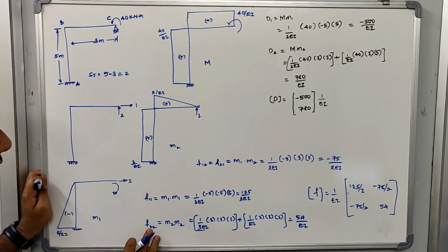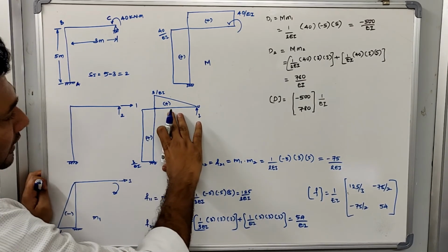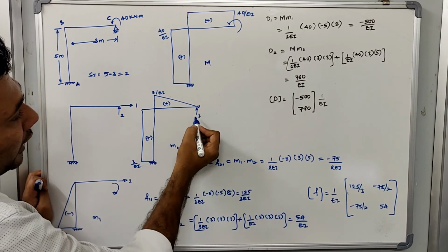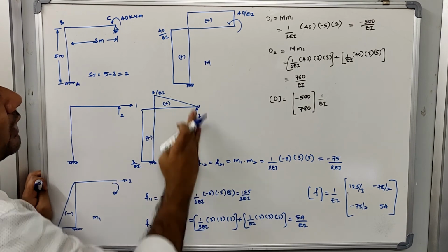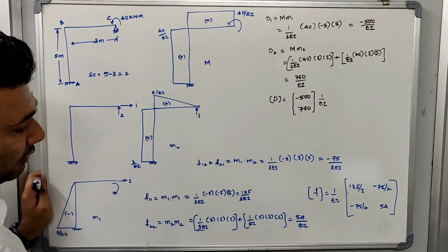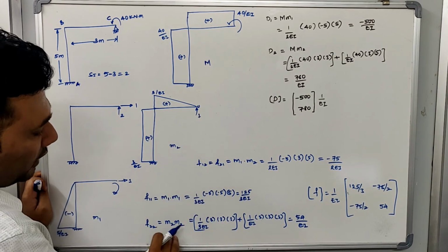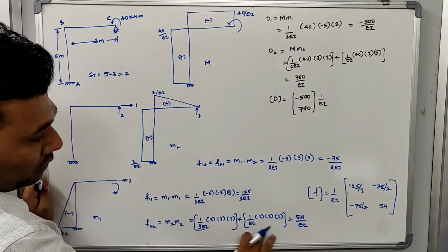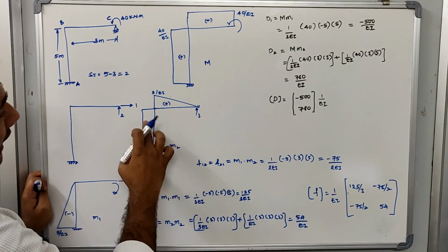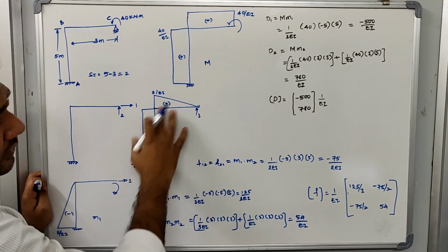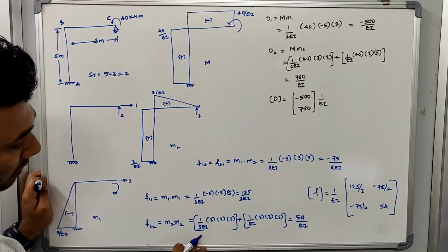So what is F22? For F22 we go to the M2 diagram. In the M2 diagram, we apply a unit force in the vertical direction and determine how much translation takes place in the vertical direction itself. So here we multiply M2 with itself so that I get to know how much F22 is. This triangle is multiplied by itself, then this rectangle is multiplied by itself, and you know the equations to solve them, they are given in the diagram multiplier. From that you can calculate F22.